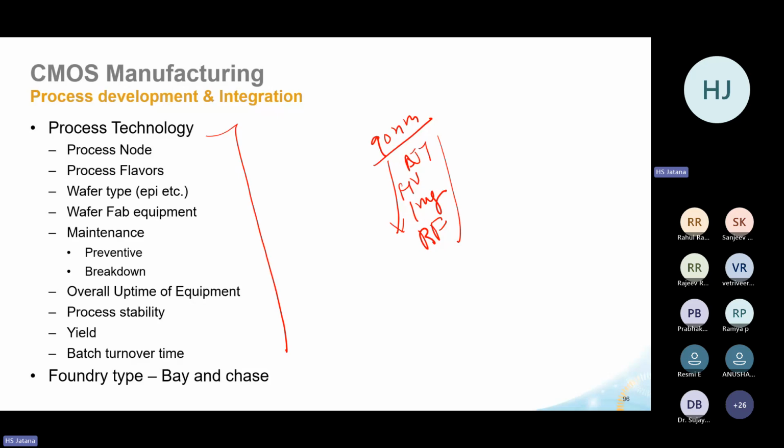What type of wafer to use, when you design the process, the process engineer has to keep in mind: what is the starting material, whether it's a P substrate or an N substrate. Then what is the resistivity? What is the doping level of these substrates? There are various types of wafer, whether there's an epi wafer, where epi may be n plus on n plus plus, n plus on p plus plus. So there are huge varieties of wafers available, and there is an SOI wafer also. And there are test wafers and there are process wafers.